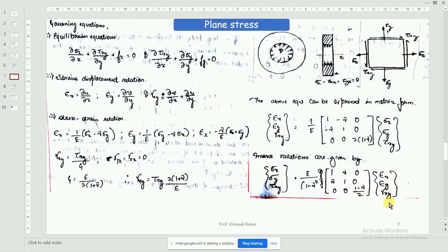So these are your plane stress conditions, and these are the equations applied to solve any plane stress problem, wherein σz will be equal to 0. It will not be σz all the time, it might be σx also, or σy also. Any one coordinate, the stress values will be equal to 0.